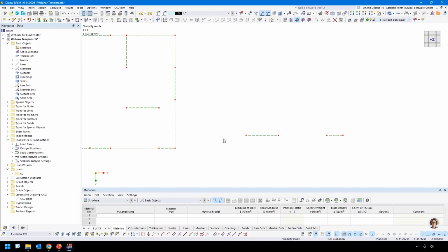In timber framing, we assume that the stiffness of the wall is proportional to its wall length. So that means when we apply 3 kilonewton on a 2 and 1 meter wall, we will get as a result this wall with 2 meters gets 2 kilonewton, and this wall with 1 meter gets 1 kilonewton. It's different than CLT or, for example, concrete or steel.